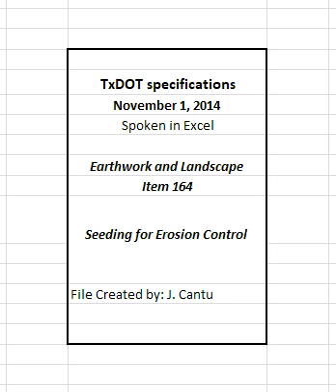3.3 Cellulose fiber mulch seeding. Plant seed in accordance with Section 164.3.1, Broadcast seeding. Apply cellulose fiber mulch uniformly over the seeded area immediately after planting the seed or seed mixture at the following rates. Sandy soils with slopes of 3:1 or less, 2,500 pounds per acre. Sandy soils with slopes greater than 3:1, 3,000 pounds per acre.